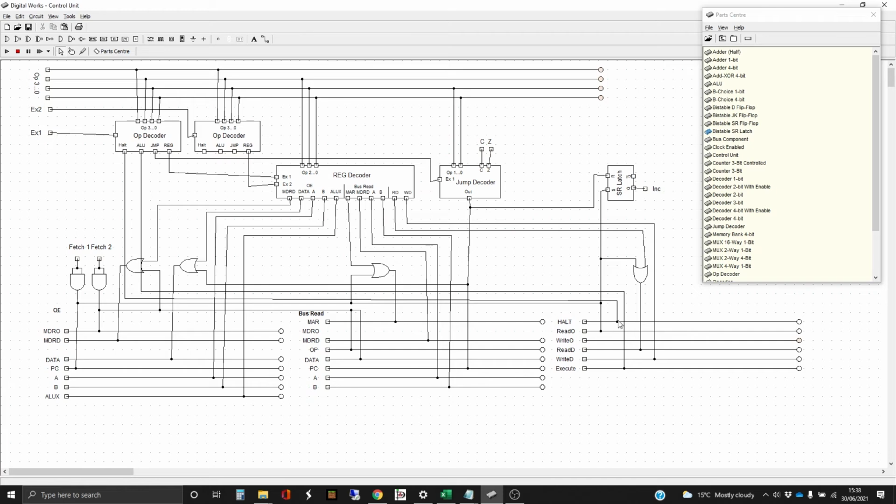Across here we've got a halt, so that's fine, that's good. We've got read from for operations. We don't have write for operations, and that again is reasonable. We don't want to be able to rewrite the program. The CPU shouldn't have the ability to do anything with that, so that's fine. Read data, yes. Write data, yes, we might want to do that.